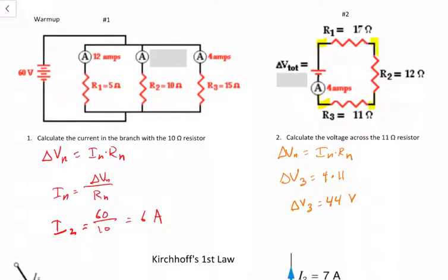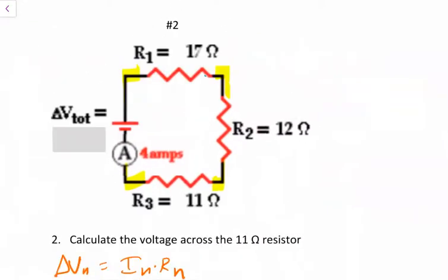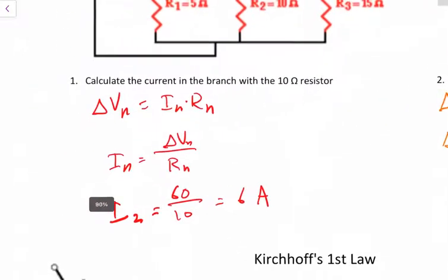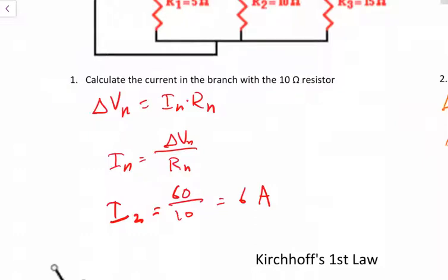All right, we see that in our first circuit we have resistors in parallel, and we know that resistors in parallel have a constant voltage across each resistance. We recognize that in circuit number 2, it's a circuit that is in series, which means it will have a constant current across each of the resistors because they're all in line with each other. The current can't be faster in one part and slower in another. They're all equal. And we're going to need to remember that the voltage dissipated across a resistor is equal to the current traveling through the resistor times its resistance.